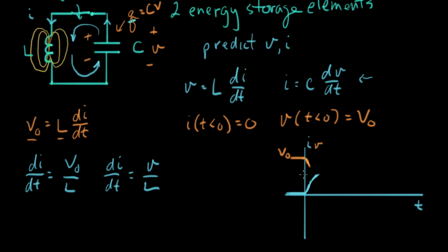All right. Now what happened next to the voltage? A little more charge has left the capacitor, headed over to the opposite plate. So the voltage is going to continue to go down. So now we're just going to edge forward moment to moment and see what happens. Every time the voltage goes down, the slope of the current gets a little shallower. And then the voltage continues to drop because the current's leaving. And eventually, that voltage is going to reach 0.